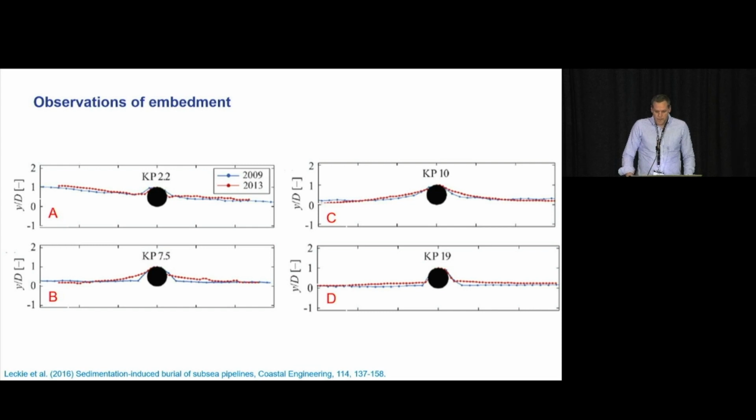So this is an example where we looked at this field data and we were thinking, okay, well, that's not actually something that anybody's reported in scour experiments before. It's not really scour, it's sedimentation, but it's definitely happening in the field, so can we explain it? And the way we did that was to look at the mid-ocean data and try and mimic in the lab the type of flow conditions, those internal wave events, and see if we could create profiles that looked similar.